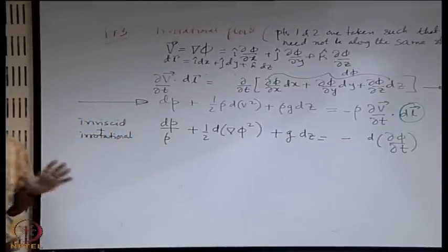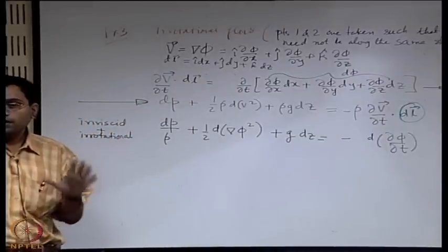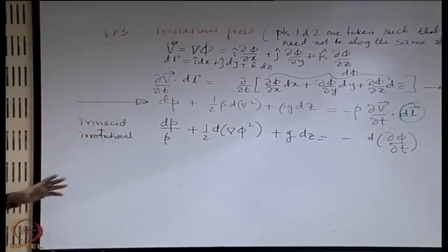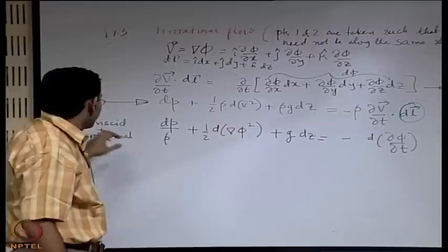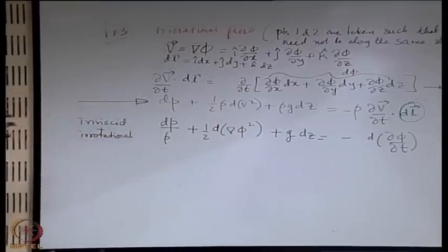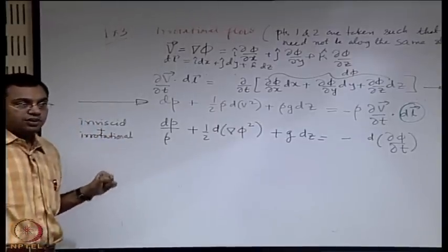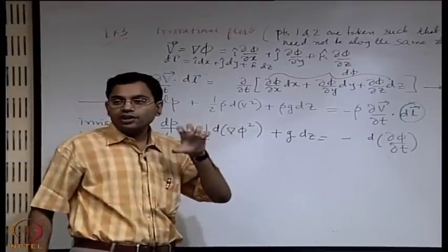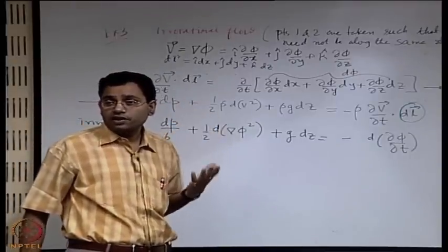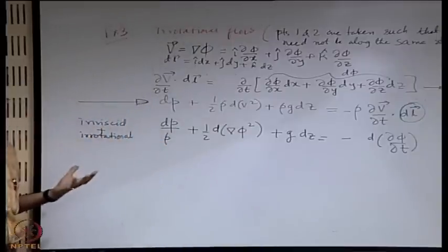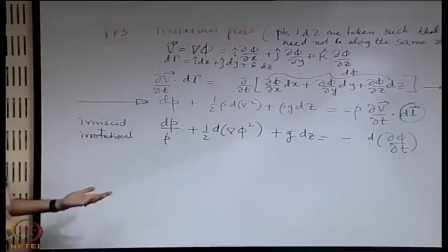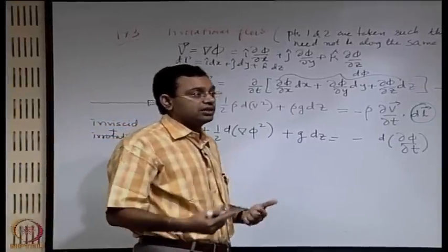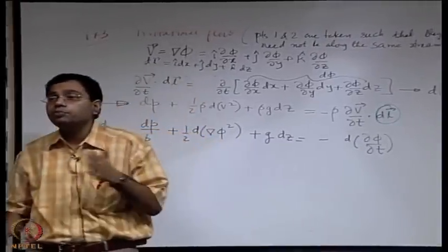Remember, these are not very simple questions to answer, and we will try to look into the very basics of these issues. Let us say that you have an irrotational flow. Say there is a free stream which is having an irrotational flow, that means it has a null vorticity vector. Now the question is, is there any agent that can make the flow go from irrotational to rotational? So will the irrotationality be preserved?